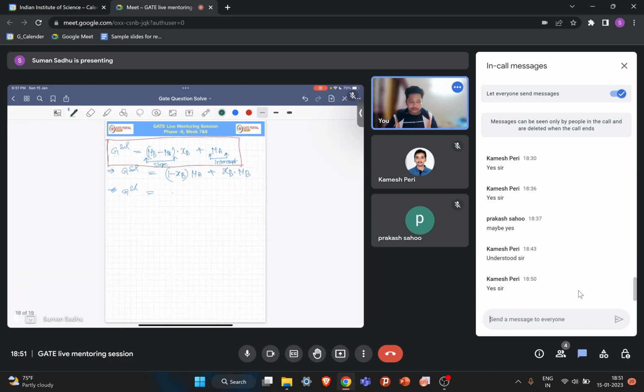But in case of miscibility, when your delta H was positive, there you saw that the delta G mixing curve looks like this, right? And if this is your GA and this is your GB, then this line is the G of mixture, and this is your delta G of mixing. So now your G of solution will be like this, right? Because G of solution is basically nothing but G of mixture plus delta G mix, right? So your free energy versus composition diagram will look like this.